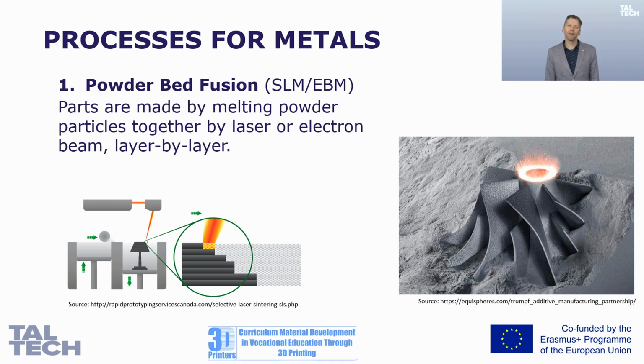Then we are melting the cross-section of the part with a laser or electron beam, and the powder particles are fused this way so that they solidify, and layer by layer the part is printed.